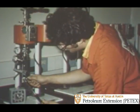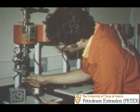The API high temperature and high pressure filtration test is made on oil muds. This gives an indication of the mud's stability. Note the filtrate, the dark brown liquid in the glass cylinder in the engineer's left hand. It should be oil with no water. If water is present, then the mud is showing signs of instability and will have to be treated.